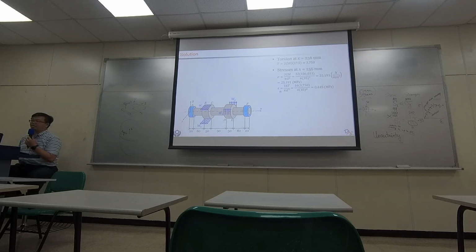How about twisting? So there, because the stress, the tension on both sides of the pulley is not the same, it's constantly twisting the shaft. So you can compute the torque, and you will realize the torque equals to, let me explain why it's this equation.